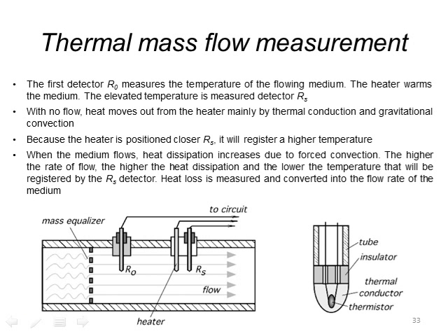So this slide shows a little bit more detail about doing these 2 types of measurements using this thermal mass. But essentially, a gas has a thermal mass. You put energy into the gas, and then you basically measure, based on the gas and the temperature and the flow rate, how much heat is being dissipated into the environment, and then you can determine what the flow rate is.